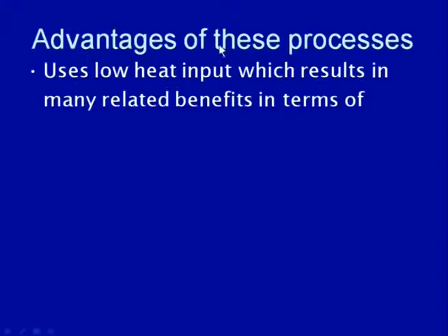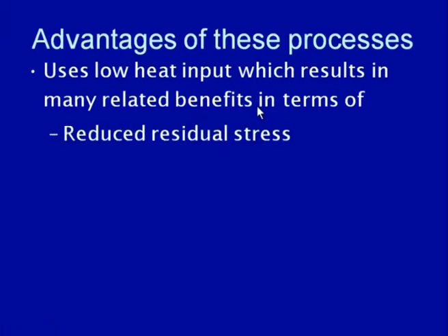being used for developing the braze weld joint. The key feature of braze welding as compared to the conventional fusion welding process is that it uses very little heat input, just for heating the edges of the plates to be welded, but not to melt the faying surfaces of the base material. And this low heat input results in a number of benefits, such as reduced residual stresses.